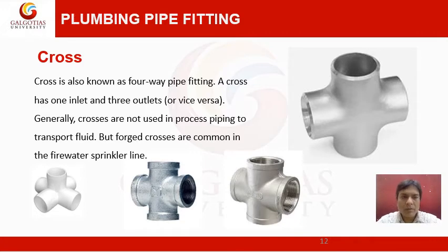Cross is also known as the four-way pipe fitting. A cross has one inlet and three outlets, or vice versa. Generally, crosses are not used in the process piping to transport liquids, but forged cross are commonly used in firewater sprinkler system.